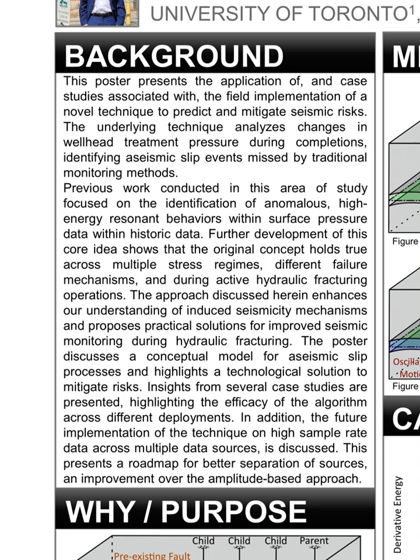To provide some background, this poster presents the application of, and case studies associated with, the field implementation of a novel technique to predict and mitigate seismic risks. The underlying technique analyzes changes in wellhead treatment pressure during completions, identifying aseismic slip events that may be missed by traditional monitoring methods. Previous work conducted in this area of study focused on the identification of anomalous, high-energy resonant behaviors within surface pressure data present in historic data.